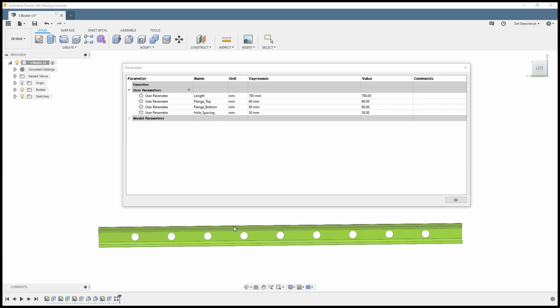So you have a choice, and you can play around with this on your own, and this is just going to be for the sake of show and tell. But if you're going to add in quantity of these, maybe you're better off not doing extent, but rather you keep the spacing and then you just keep adding holes yourself by hand, or you tell it to go to extent and then you just keep adding holes until the spacing looks okay to you. Except, I mean, these are lightening holes, so you've probably done the engineering on how far they're supposed to be, the diameter, et cetera, and so forth, right? So whatever you choose there.